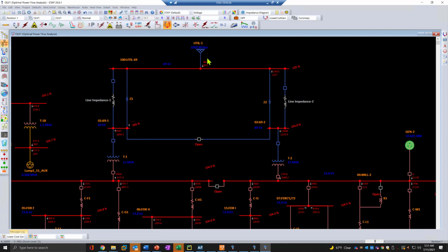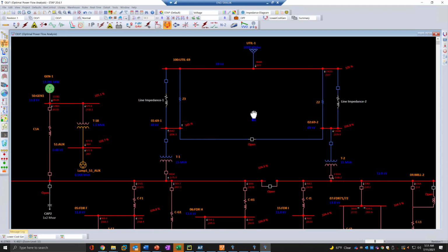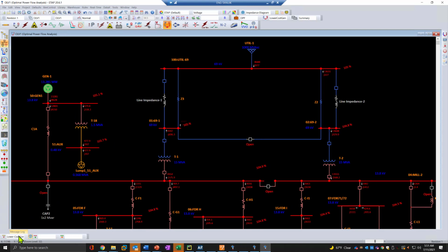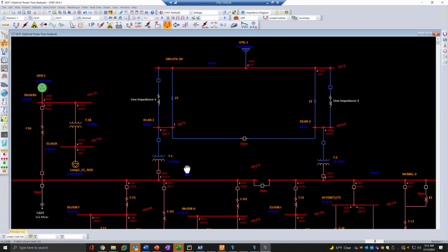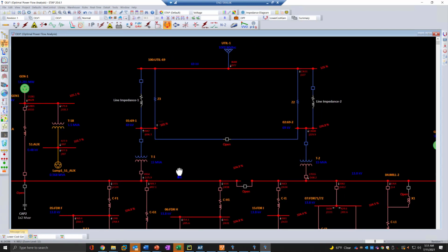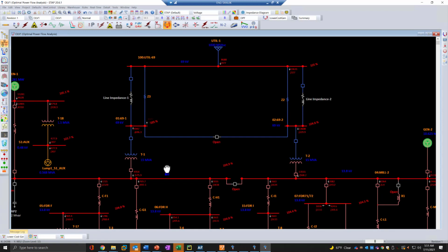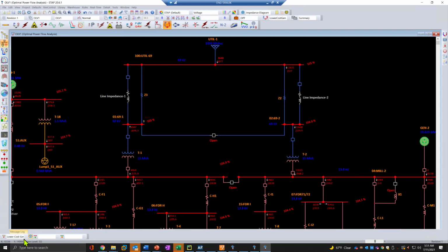The grid power goes from 3 megawatt to 8.6, and generator 1 takes up maximum load and reaches its rated limit of 13.281 megawatt. So this is a case where we are setting up the program such that generator 1 is the cheapest source of energy and you can see how OPF rebalances or redistributes this within the network.